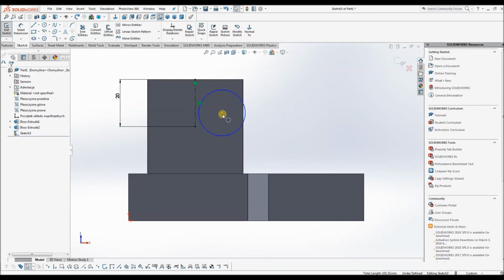But I just found that it will be easier for me to make the center line. Also, when it's the center line and we want to make this thing wider, it will still be on the center. It will be 20 from here, so when we extrude it, for example, for 50, it won't be in the center, right?